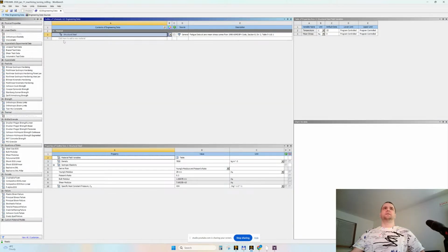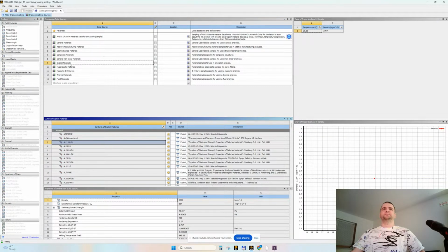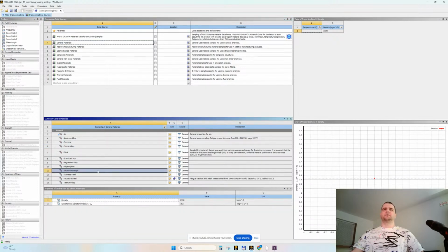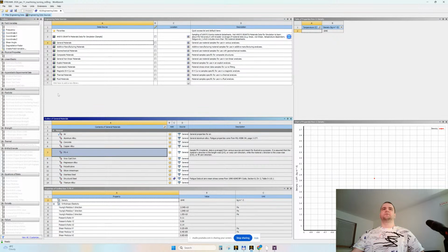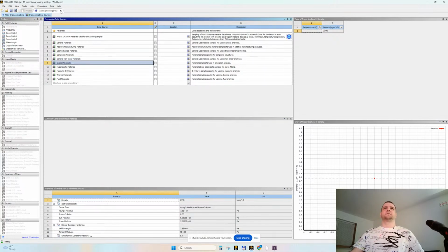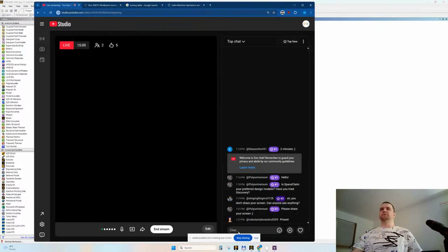So what I did, I didn't do anything here because I remade the model from scratch. I prefer to go on explicit materials and add an explicit aluminum. Don't use linear materials when you are exceeding the large deformation domain. Don't go here, don't choose here. Instead, go on either general nonlinear materials or explicit materials. Double click. Now the model should load.